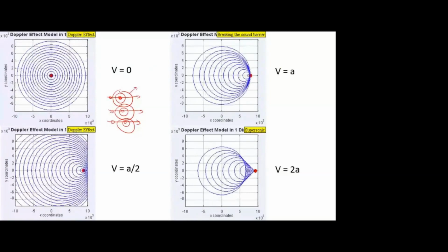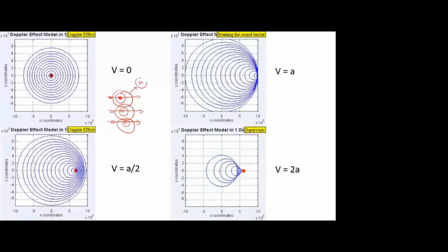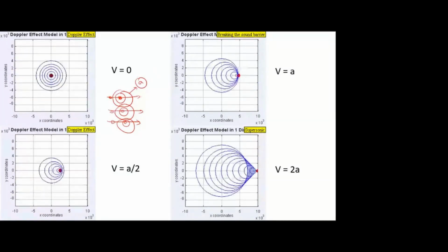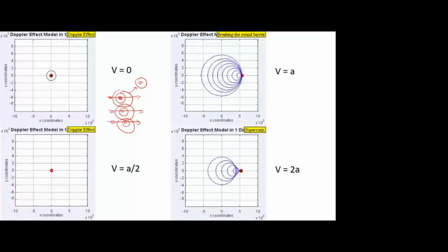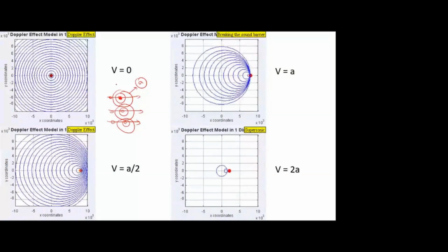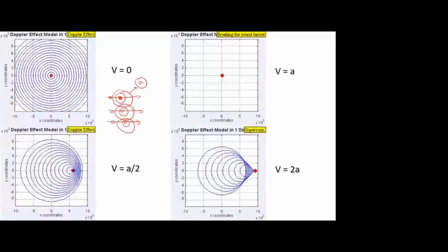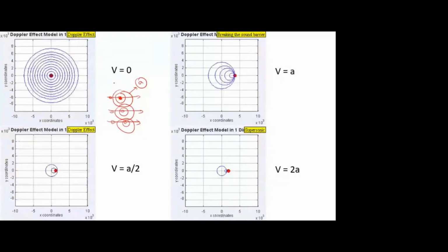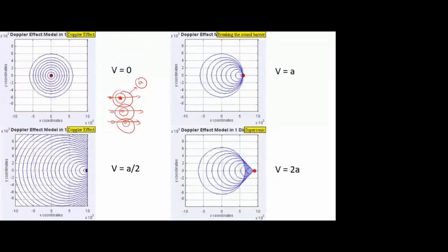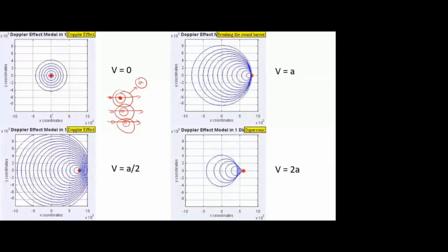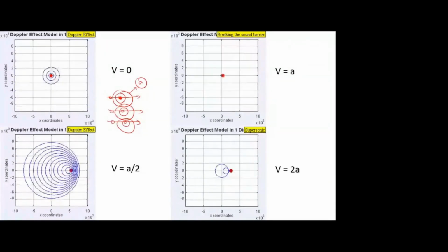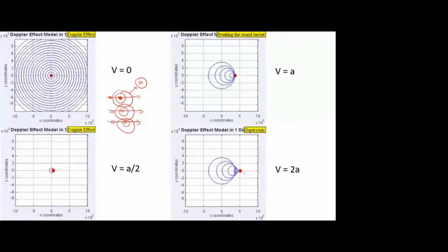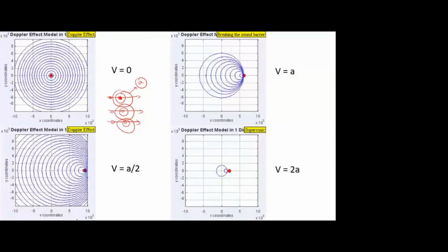And you know the speed of the pressure waves, the sound waves: sonic speed, A. So here we are discussing the wave emitted by a single fluid particle. In the book, they call this disturbed fluid particle a point disturbance. So here we are discussing the point disturbance at different speeds. Here it is at rest. Here it is moving at subsonic speed. Here the point disturbance is moving at sonic speed. In the fourth one, it is moving at supersonic speed.